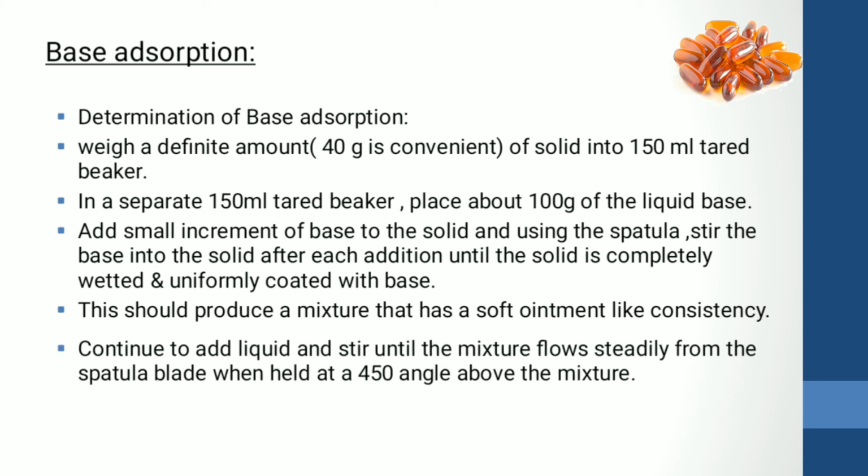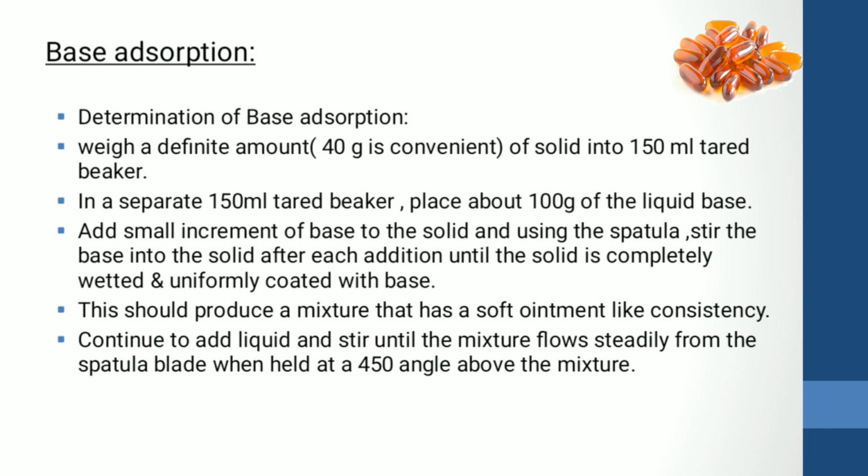Then continue to add liquid and stir until the mixture flows steadily from the spatula blade when held at 45 degree angle above the mixture. Then base adsorption is equal to weight of base upon weight of solid.